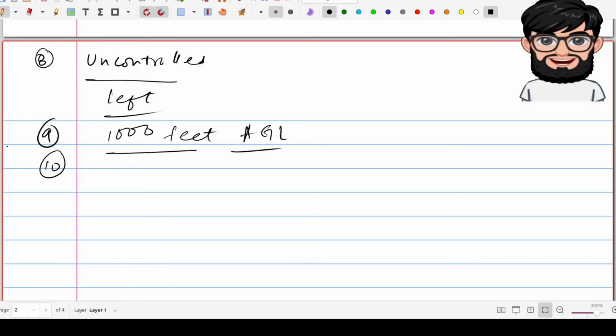You should not be entering the traffic pattern where your altitude is not settled; it should be level flight. And when departing a traffic pattern, continue straight out or exit with a 45-degree turn. These are the recommended ones.